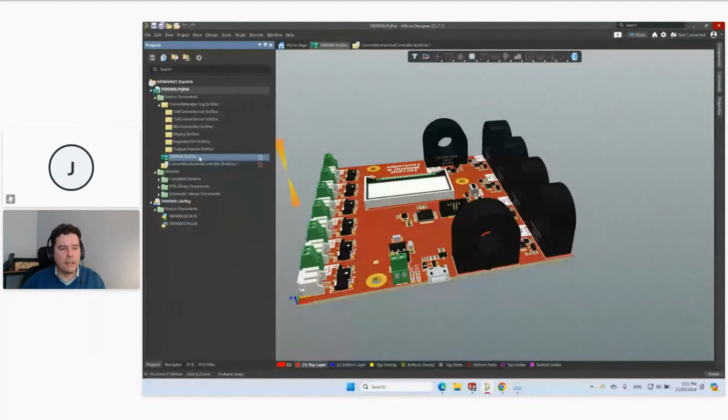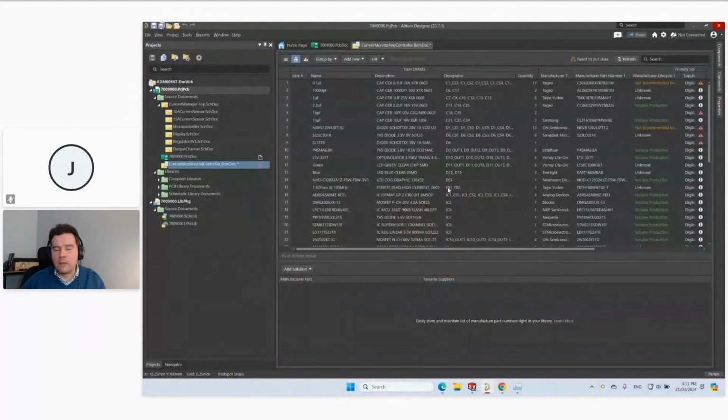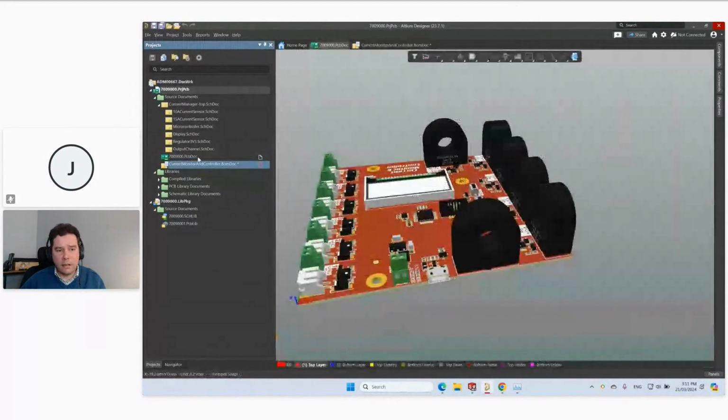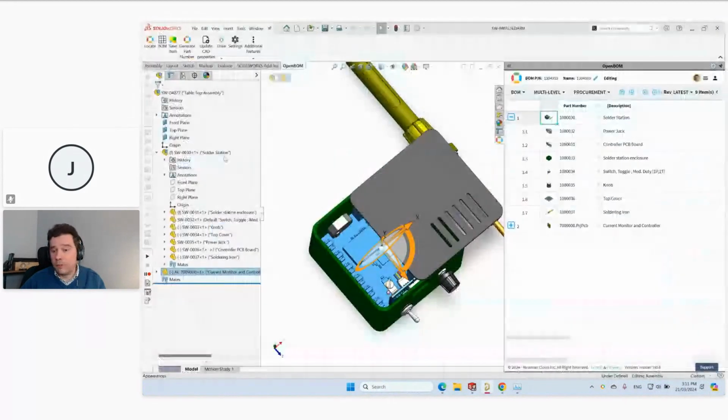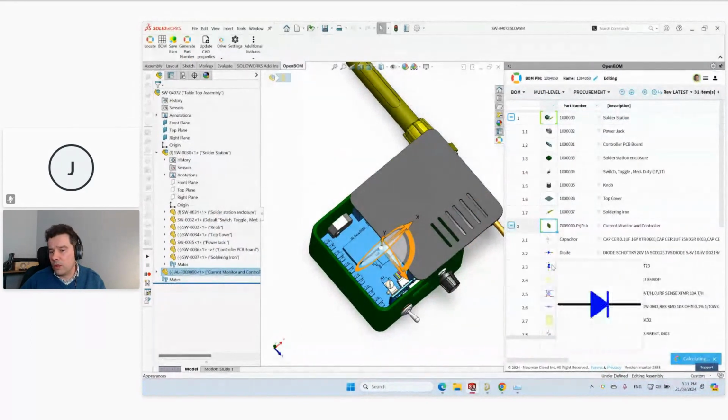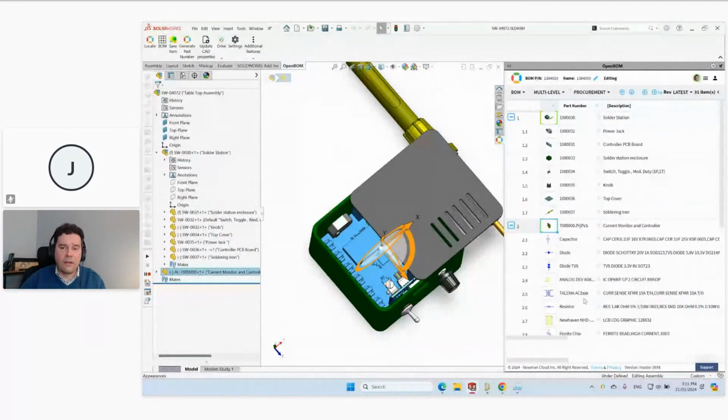There's a BOM in Altium already with all these items on it, and you can see a complete full product structure or bill of material, even from inside SolidWorks. Notice that the children were all updated by Altium, since Altium has the same part number. So you can have a complete full product structure inside SolidWorks and collaborate with multiple teams from ECAD and MCAD.